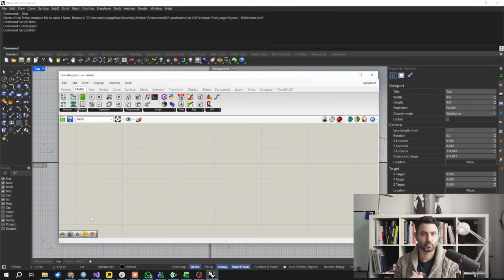That's why, for me, from my point of view, there is a limit to Grasshopper, right? When I say a limit, I mean I talk about a complexity limit. So there is a certain type of complexity that you can reach with Grasshopper, but when you start to push over that, that's really hard. And secondly, it's a problem of speed, right? So everything you manually draw here needs to be translated into some kind of code behind, and then that code gets executed. So you're losing a lot of time with this translation. Yeah, so everything is much slower if you do it in Grasshopper than in code.